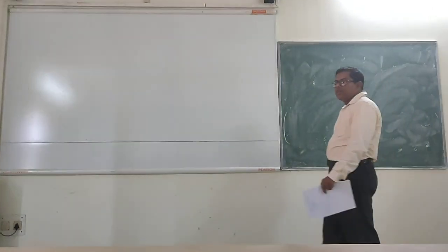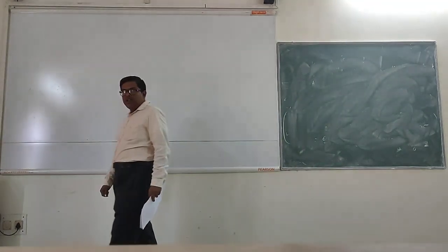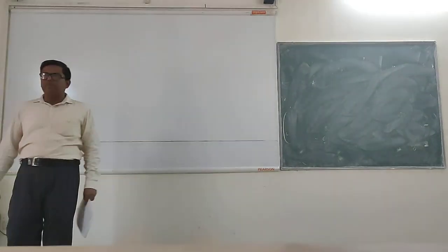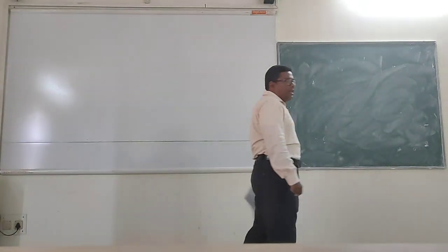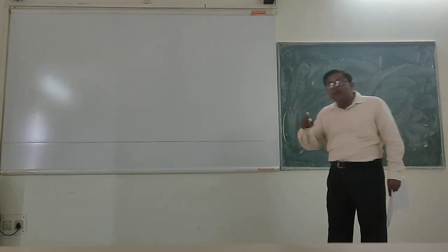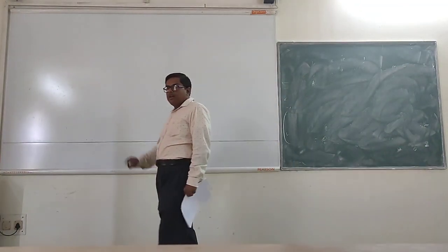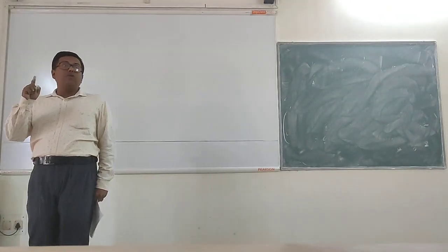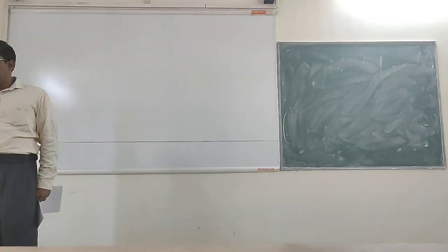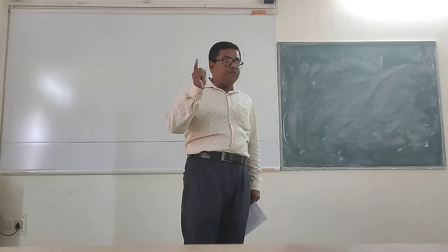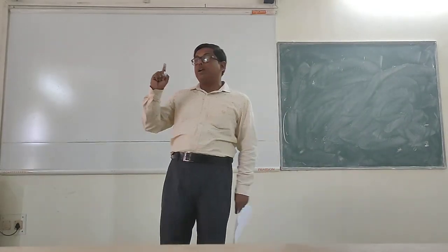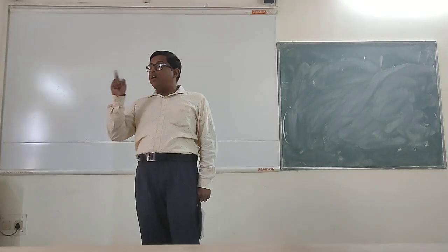We were discussing the deflection calculation in beams using which method? Macaulay's method. And basically it is nothing but the double integration method. In Macaulay's method, you have seen that if there are multiple concentrated loads, and you want to solve using direct double integration method, then what will happen? You will get multiple constants, and for that you need multiple boundary conditions, which is very difficult to get.